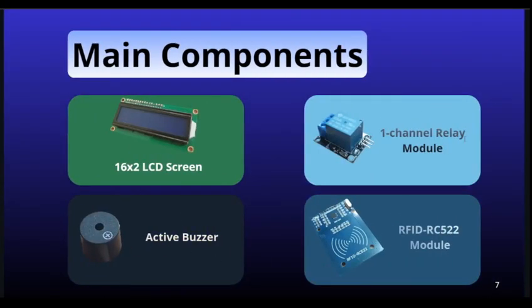The hardware ecosystem is complemented by these four peripheral components. First, the 16 times 2 LCD screen. It is our main user interface. It is based on the standard HD44780 controller, and we drive it in 4-bit mode from the PIC to optimize pin uses.